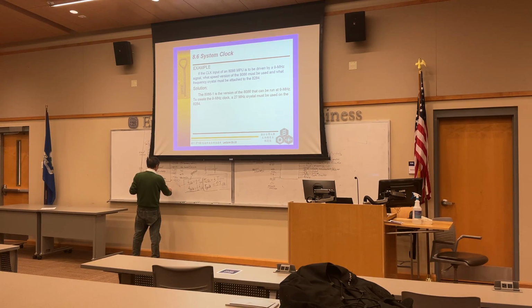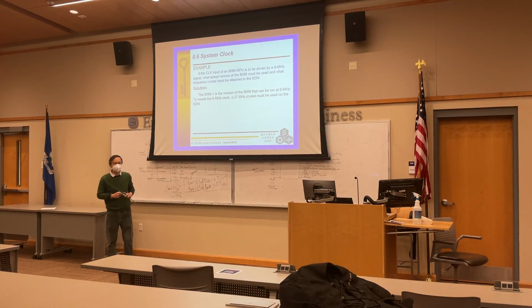F oscillator equal to what? Equal to 3 times the F clock. Equal to 3 times 9 megahertz. That means you need to purchase a quartz with 27 megahertz oscillator. Is this okay?